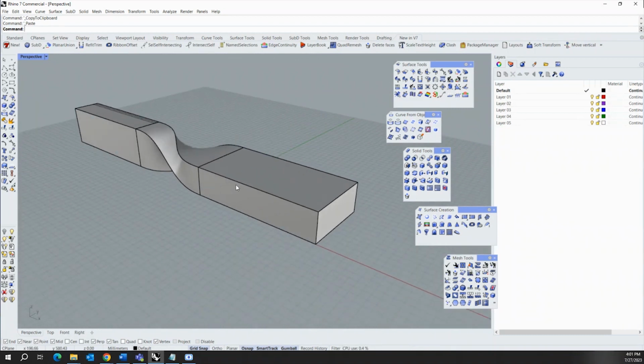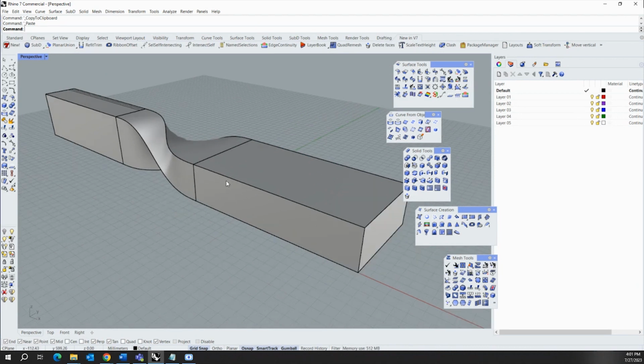Then similarly what I have to do is I need to take the line here also, like I need to give the fascia of this building, right? So for that, I can draw the line also. That is one possibility. The other command which I can use is I'll go to this control points tool. I'll click this. You can see this duplicate edge. If you click that and click this edge, it will give you the duplicate edge of this. So you can select that and move this by 50 mm. I think it's going up. 50 mm downwards you need to do.